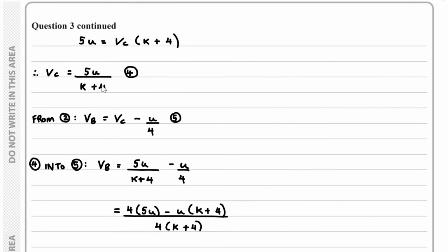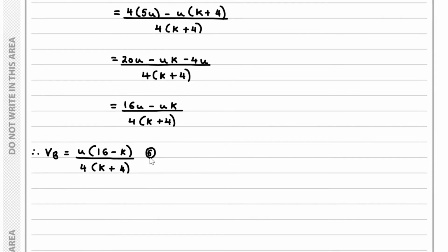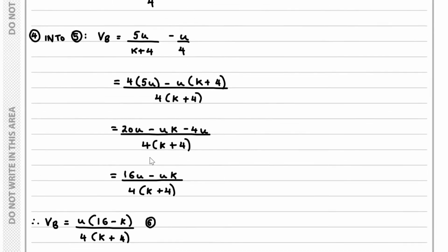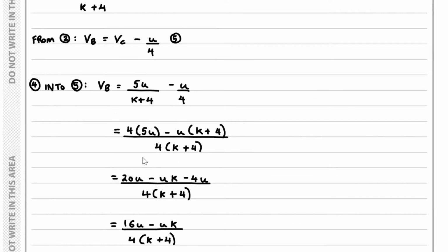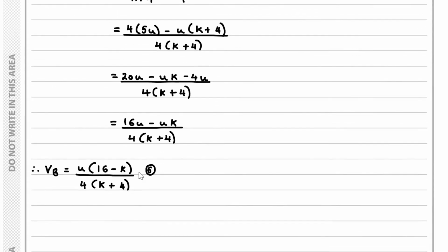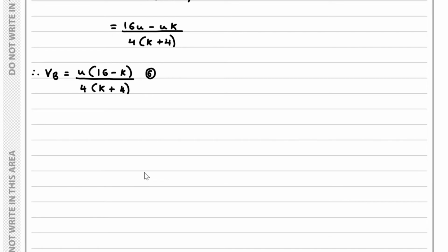In other words, that tells us that C moves off with a greater speed than B, and B is still moving towards the right, but there'll be no further collisions. So therefore, vB is going to be greater than or equal to 0. It could equal 0 because it could just come to rest completely.